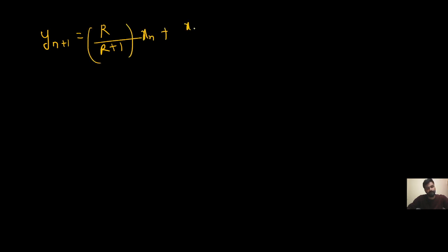Now the next topic of discussion of this video lecture is the use of the operating line. One more important thing I would like to say here: whenever we calculate the composition in the stripping or enriching section of the distillation column, the equation of the operating line of the enriching section is y n plus 1 is equal to R upon R plus 1 x n plus x D upon R plus 1, right? So I am assuming this is equation 4.